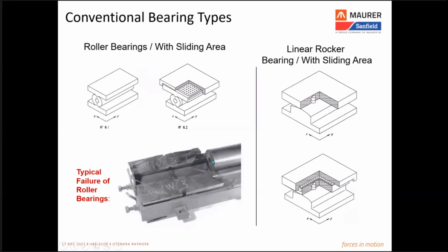But these bearings cannot offer any rotation in the transverse direction, because the long roller prohibits the bearing from tilting laterally. So there the degree of freedom is restricted. And sometimes, due to concentration of loads, the rollers, because they have a point load contact, give way, which adds another demerit to this bearing system.